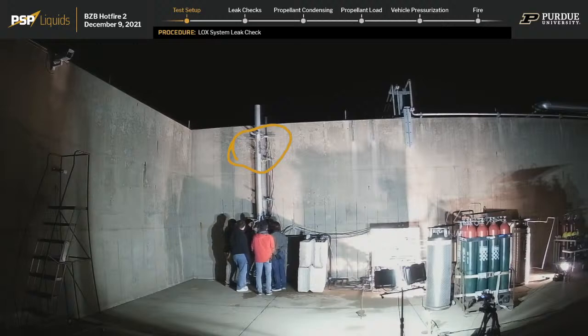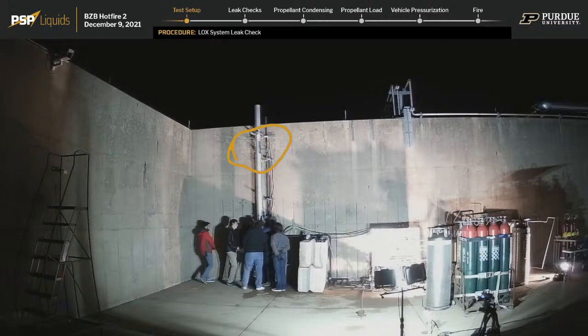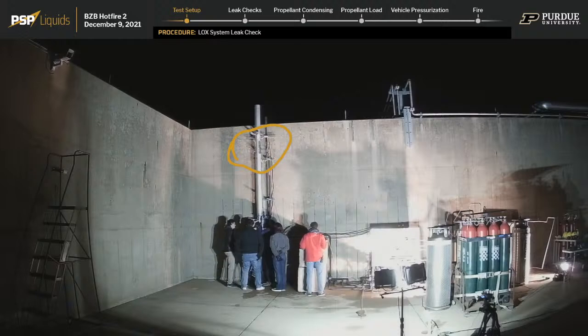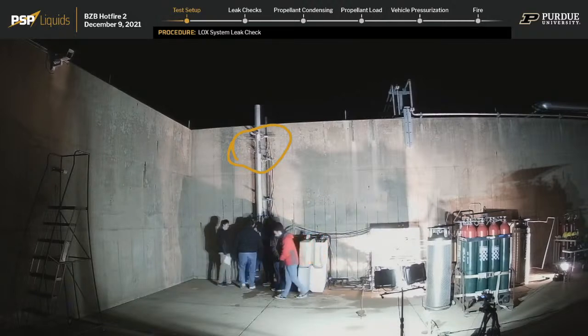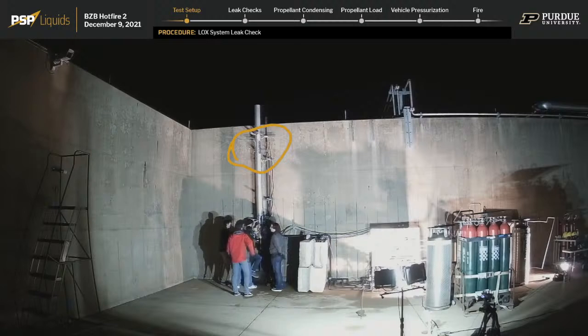So, our system, Boomie Zoomie B, is a liquid-fueled rocket that utilizes a pressure-fed design cycle. The idea of a pressure-fed rocket is that instead of having pumps to feed fuel and oxidizer into the engine, you use gas pressure from an upstream source. In our case, we are using a high-pressure helium bottle and diverting that helium into the methane and oxygen tanks.